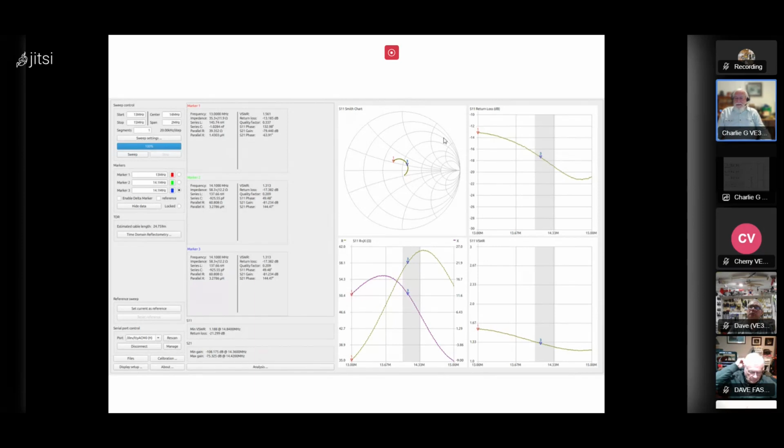So once all the foul weather is out of the way, I'm going to go up on the roof and cut a few feet off of it, and that should get it back to the middle. But to be fair, the standing wave ratio has gone down to 1.3, which isn't bad. It was nearly 3 previously, so it's doing its job.